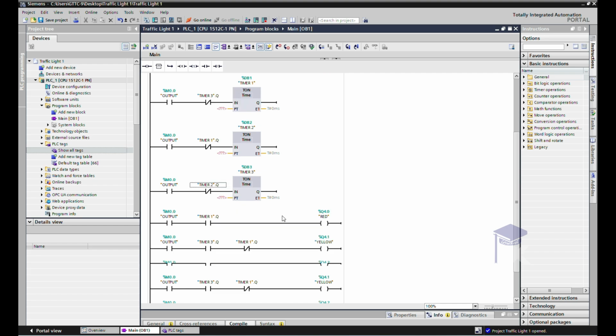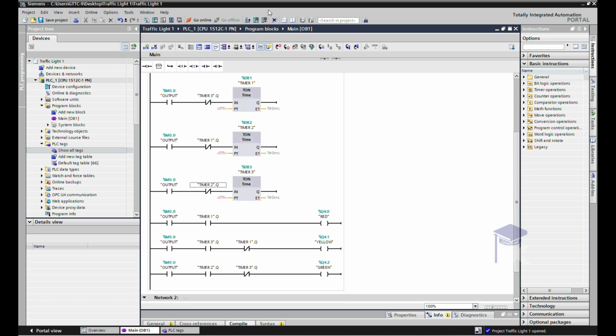When green starts, then yellow should stop. See, if you do not add an input as address, it will show an error. Then simply click on it, go to this option and assign the value as input or output. In our application it is output, so assign it. So after assigning,